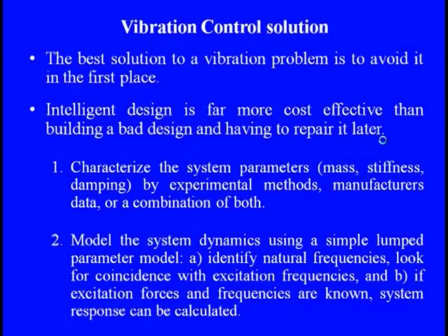So you see here there are processes in which we can adopt the vibration control solution straightaway. First, just to characterize the system parameters, as we know there are three basic things under any dynamic action, and these forces are always dominant, and we need to characterize this. So we need to characterize the system parameters based on the mass, the stiffness at the contact regions according to the deformation, and the damping of any nature: intermolecular, structural, or any kind of fluid interaction.